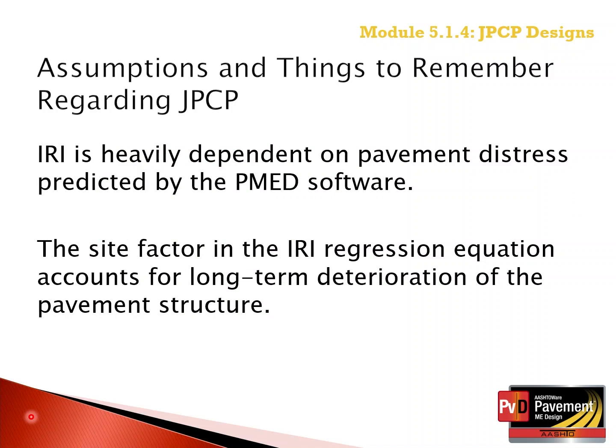Another thing to remember, the functional performance of the pavement is estimated through the calculation of IRI throughout the design life. IRI is heavily dependent on pavement distress, as well as the site factor for some climates and soil combinations.